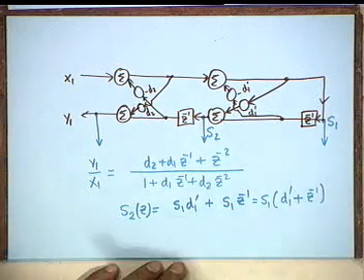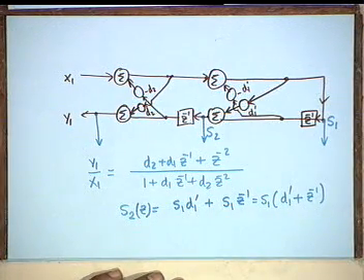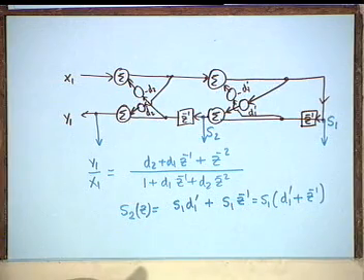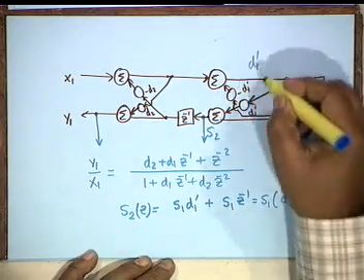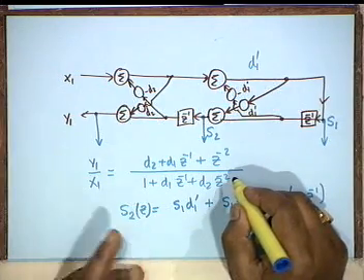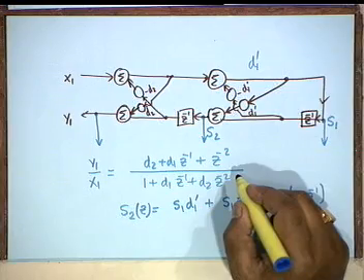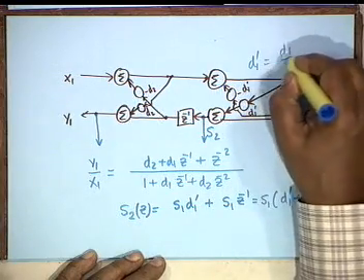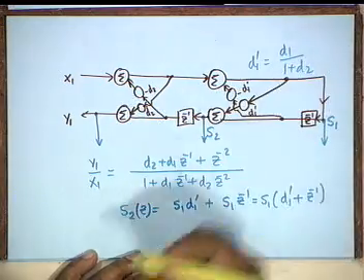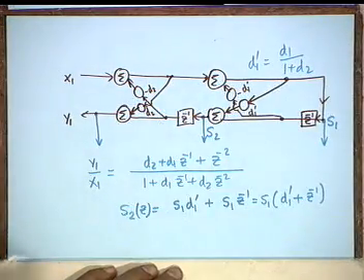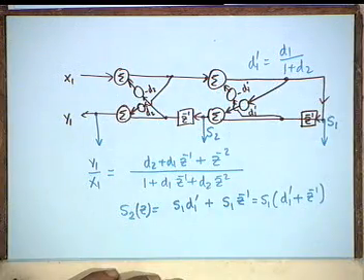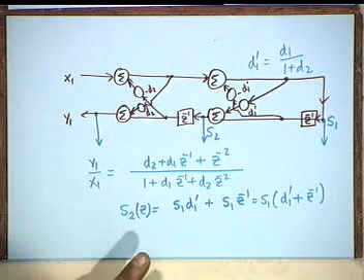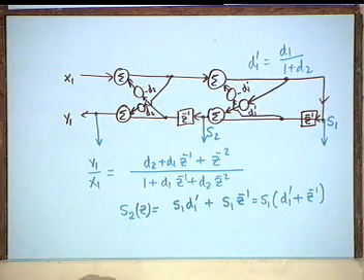What is this polynomial D1 prime plus Z inverse? It is the numerator of the first order all pass function, isn't that right? What is the relationship between D1 prime and D1 and D2? D1 by 1 plus D2. Both of these shall be useful as you will go through. It is a very beautiful derivation, first given by 2 gentlemen by the name Gray and Markel.